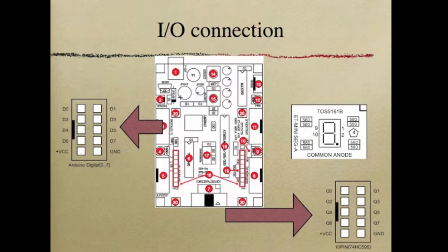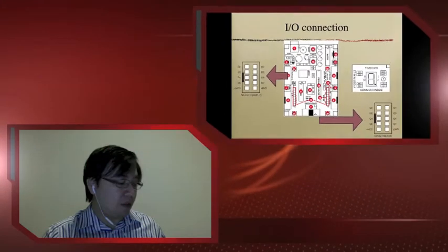For our Arduino board, the 7-segment is designed to connect to the 10-pin connectors. You can just plug in your 7-segment to the 10-pin connectors, like this. Just plug it in. Alright. However, this pin is a special port, so I have already provided you a special code that will allow you to pass data from the main AVR chip to the chip register and then to the port. You can just use it.